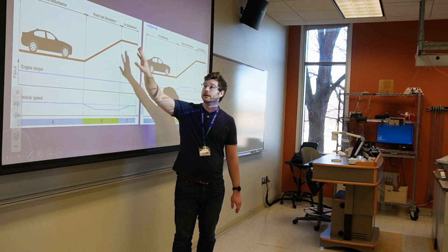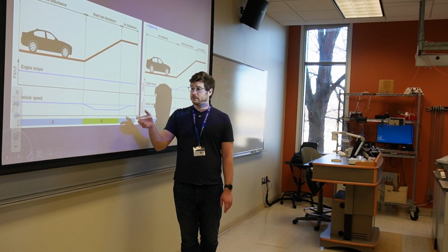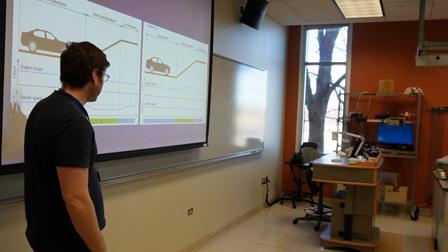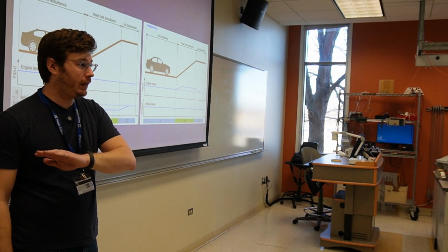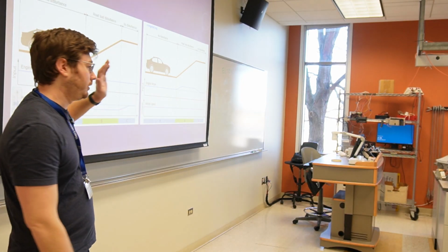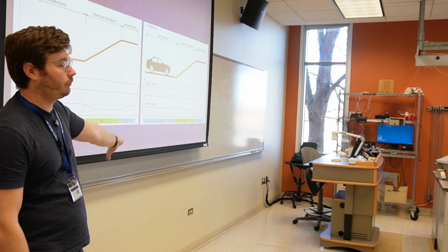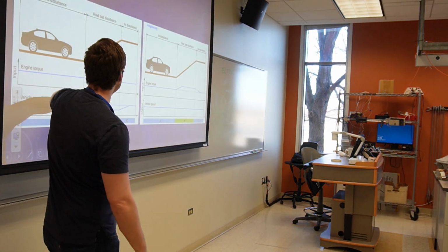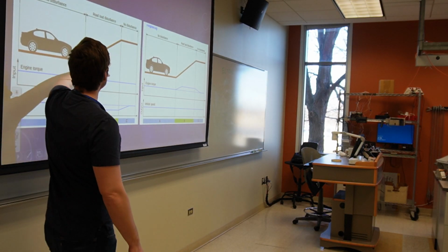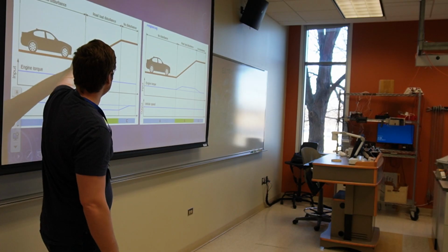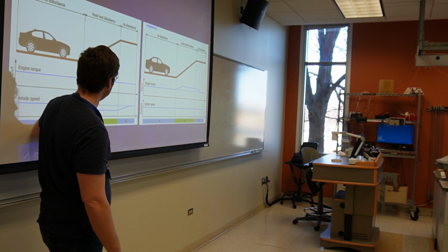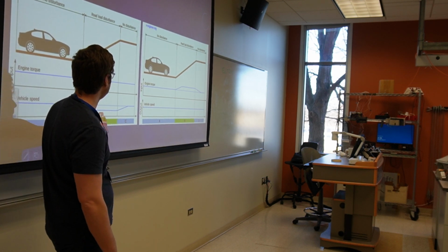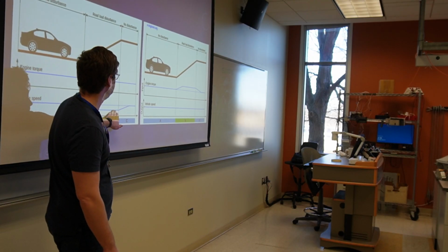You're kind of trusting that your output is what you tell it to be. It can't deal well with disturbances though. So for example, in our ideal situation, if we have a controller that's saying, okay, on an open flat road in the desert with no friction, I can run the motor at 2,500 RPM and I know I'll be going at 50 miles an hour. So I should rev that amount and that'll be good. But if it hits a bump in the road, or here when it hits a hill, that naive approach, that open loop, doesn't account for that hill. So when we hit it, the car slows down as a result. We're still driving the motor with the same amount of force. We have a small disturbance here. We have a small amount of error, a difference between our set point and the actual reality.